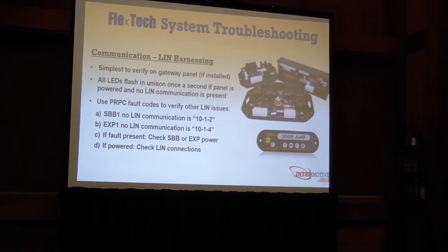So I was saying earlier that LIN, that single wire serial communication, is switching 0 to 12 volts. Depending on the communication on that wire, you're going to see 9 to 10 volts on that cable. So if you want to use a meter to verify that, you can do that as well.